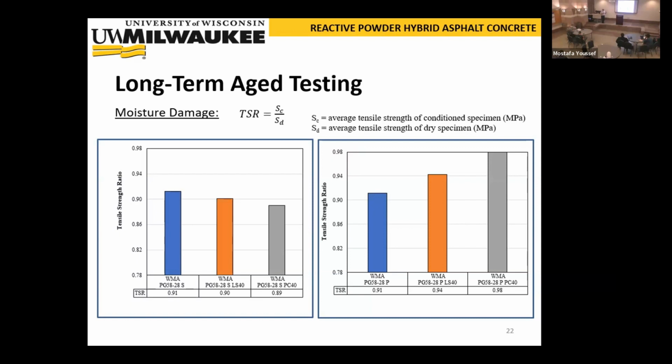And it makes sense because you're adding cement into moisture, so the hydration starts. This is the exposure to moisture, it takes a long time. And once you move to the polymer modification, you almost don't see any moisture damage. The tensile strength ratio is 98%, so it didn't lose anything of its tensile strength, which is critical in resisting stripping and is also an indicator of crack resistance. So what we saw at the binder phase, which was giving us mixed results, seems to be showing the opposite at the mixture level, at even higher concentration.